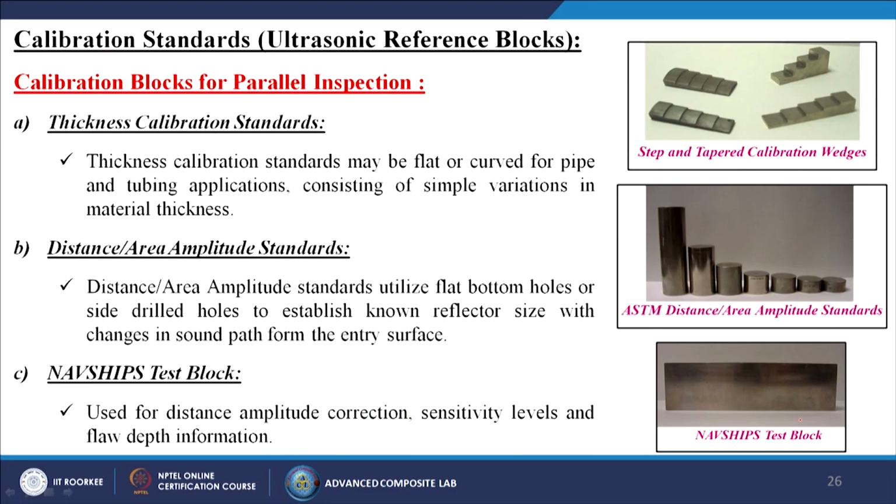Next, calibration standards, ultrasonic reference blocks. Calibration blocks for parallel inspection. First one is called the thickness calibration standards. Thickness calibration standards may be flat or curved for pipe and tubing applications, consisting of simple variations in the material thickness. Here you can see step and tapered calibration wedges.